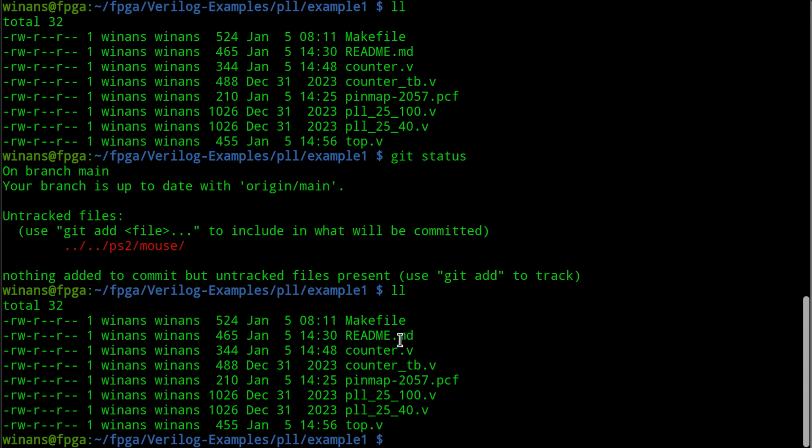So look at what's here. See these two guys here? These are the PLL modules that have the hard macros in them. And these I hacked myself by hand because, among other things, I'm going to show you how to use the gbuff output thingy. With the tools that come from Yosys, you have to do this by hand, as far as I know.